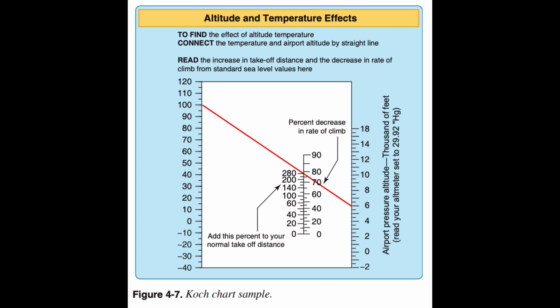The magnitude of the force of lift is directly proportional to the density of the air, the area of the wings, and the airspeed. It also depends upon the type of wing and the AOA. Lift increases with an increase in AOA up to the stalling angle, at which point it decreases with any further increase in AOA. In conventional aircraft, lift is therefore controlled by varying the AOA and speed.